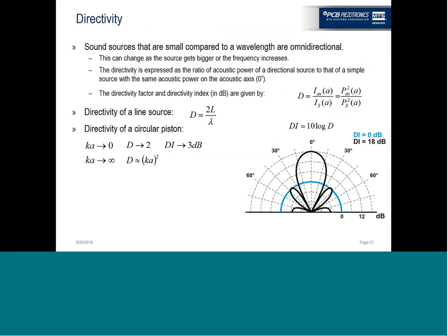So I'll talk about directivity here. Once you have your source, and let's say you've worked on a noise source or you're looking at a noise source, what you want to know about it is where the sound is coming from on the source. And intensity can give you localization, but also what it can give you is the directivity of a particular source.